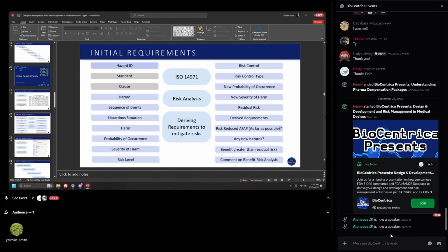So it has a mitigation in a way that even if all of our safety systems fail, the maximum that it can go to is 50 degrees Celsius because there's already limited power to it, right? But even then, we have added a temperature sensor and a temperature limiter, the appropriate word for it, that can cut off the power to the heater.